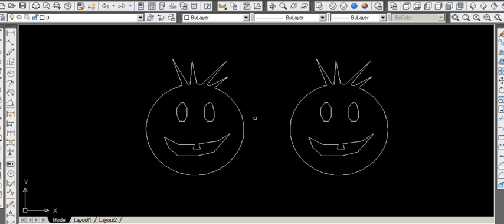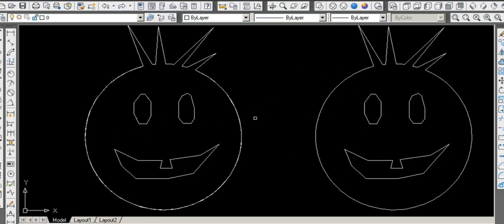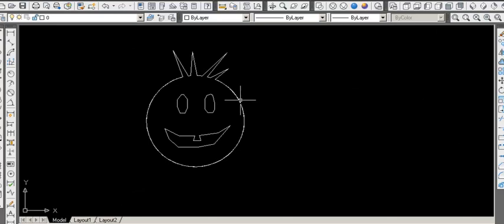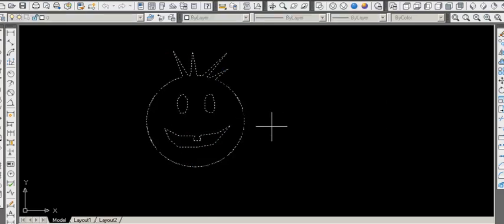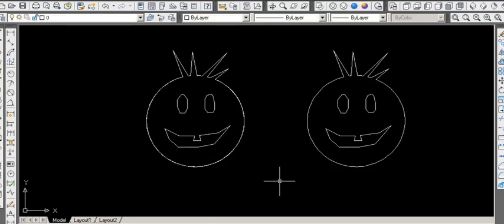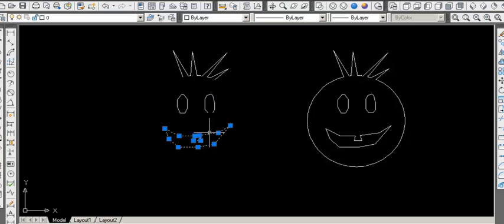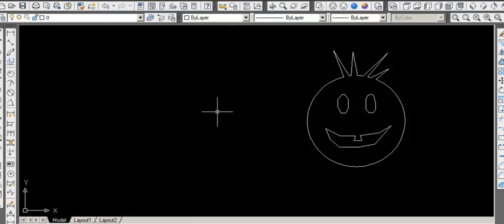That's why you saw me, and I'll back or undo back, that's why you saw me click on one component at a time, not doing a box selection, but one component at a time, and doing a move command and moving it off. Then I can go back and delete all the original geometry that was built in with it. And you can see that every time I did that boundary command, it created a new component. So I'll delete it all there.